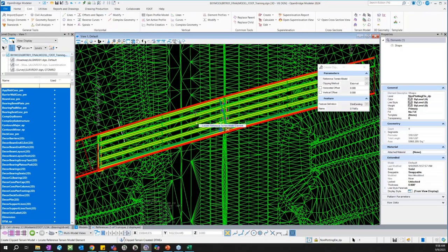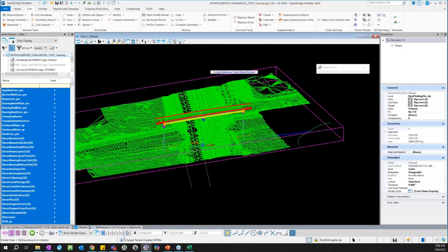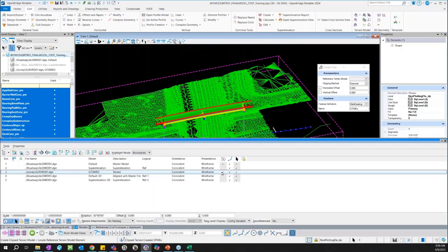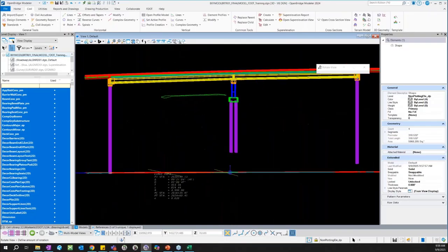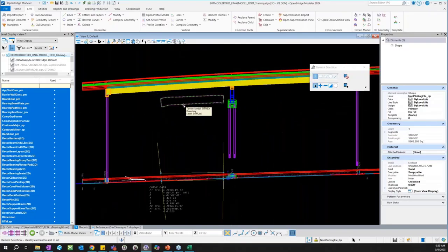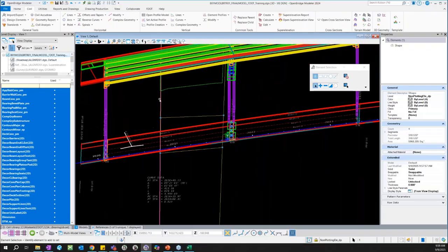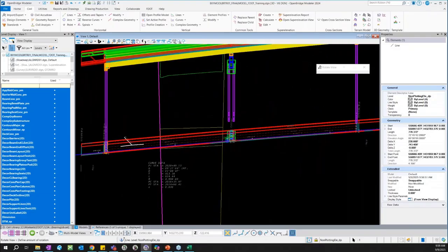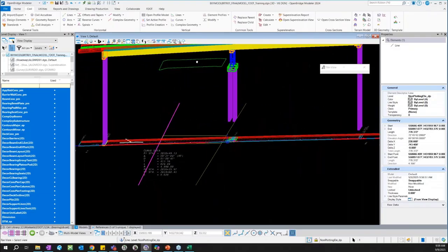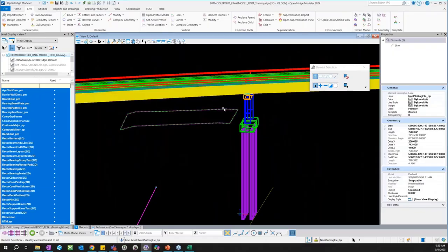And now it should have a clipped terrain, a copy of the clipped terrain. You can see I've turned off my terrain file, but I still have this clipped terrain. It makes a copy of the terrain using the clipped boundaries that I defined based on my fake gutter lines, to help us isolate the area that we are interested in for our vertical clearance check.